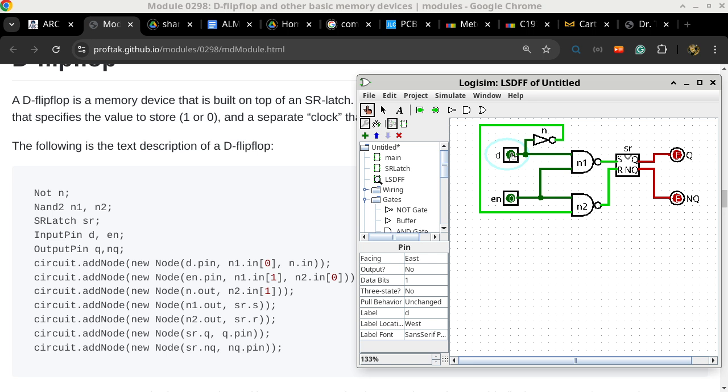As a result, the SR latch sees its input as both ones without being exposed to one of the other configurations before. And as a result, the SR latch does not know what it is supposed to remember. You're telling me to keep the state of the output, but what was it? We never specified. Is that okay?